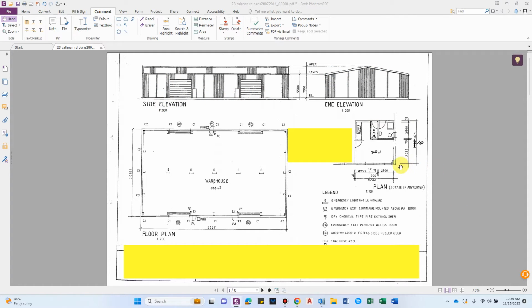So before starting we should know a bit of an idea about the portal frame design. So as I said, we'll be considering the portal frame in this direction. So this elevation gives an idea about the portal frame. So we'll have a column here, over here, and this being the rafters, or we can say beam. So this is the portal frame action, and that is how the lateral stability along this direction is achieved.